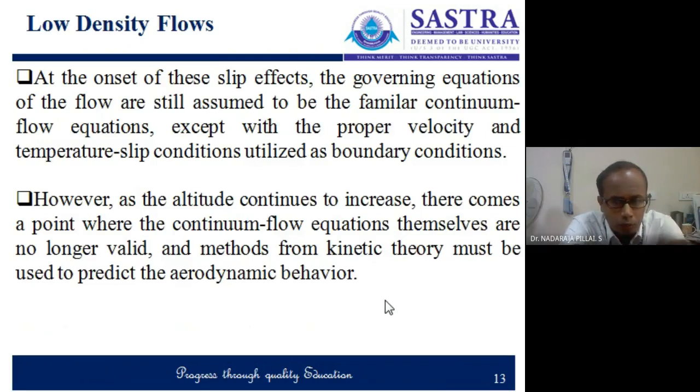However, as the altitude continues to increase, there comes a point where the continuum flow equations themselves are no longer valid, and methods from kinetic theory must be used to predict the aerodynamic behavior, right? So, increase in altitude, decrease in density, increase in the mean free path, and with all those things we need to consider kinetic theory instead of the continuum process.